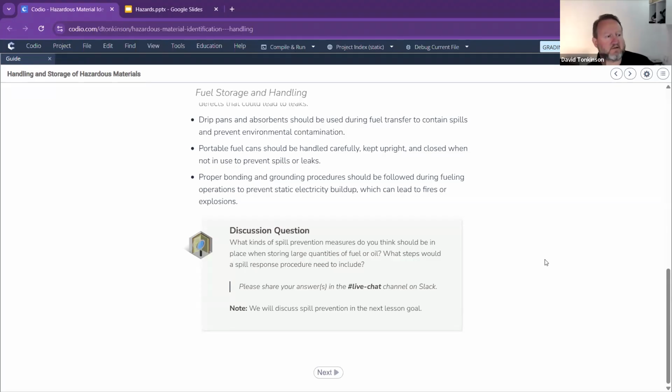Storm drain covers, secondary containment. Look at that. Fredo, it sounds like you worked in one of these before. Storm drain covers, secondary containments, regular inspections, and overfill prevention measures. Yes, we need overfill prevention measures. Monoxide detectors, certainly from Stephen. If we are running a diesel generator in a confined area, we need to make sure that we are not going to gas anyone who walks into that particular confined area.